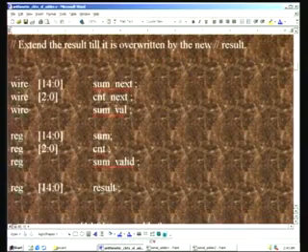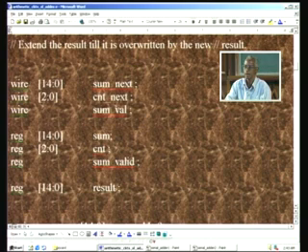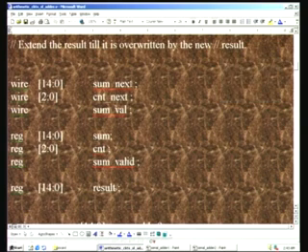We have also to declare wires and registers. The wire, as you know, is actually the assign statement's outputs. These are all the intermediate outputs that we need prior to registering later on, and you have a 1-to-1 correspondence between sum next, which will do the accumulation of the different numbers. For example, n0 emerges first, then this will be n0 after summing, and prior to that we need to initialize this to 0, and we will see that will be done only in this sum case, which is a registered case. As we progress we will see the difference.